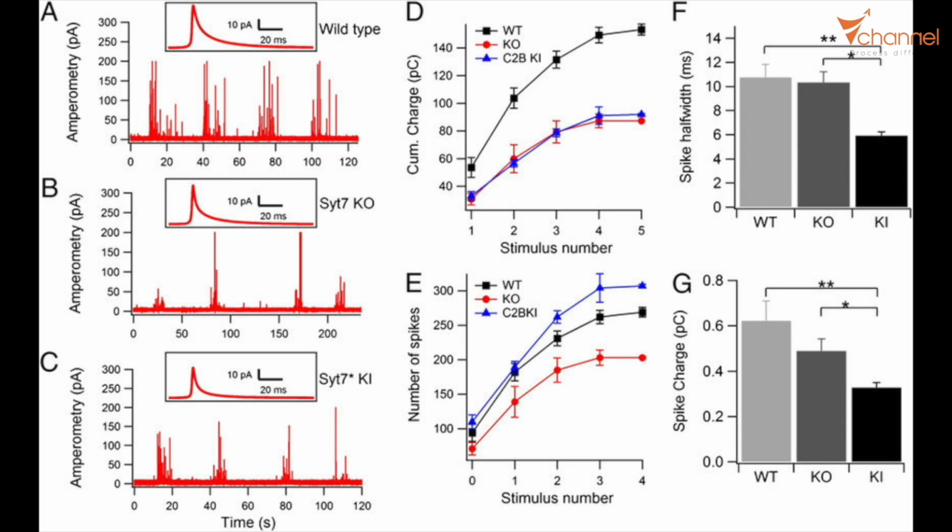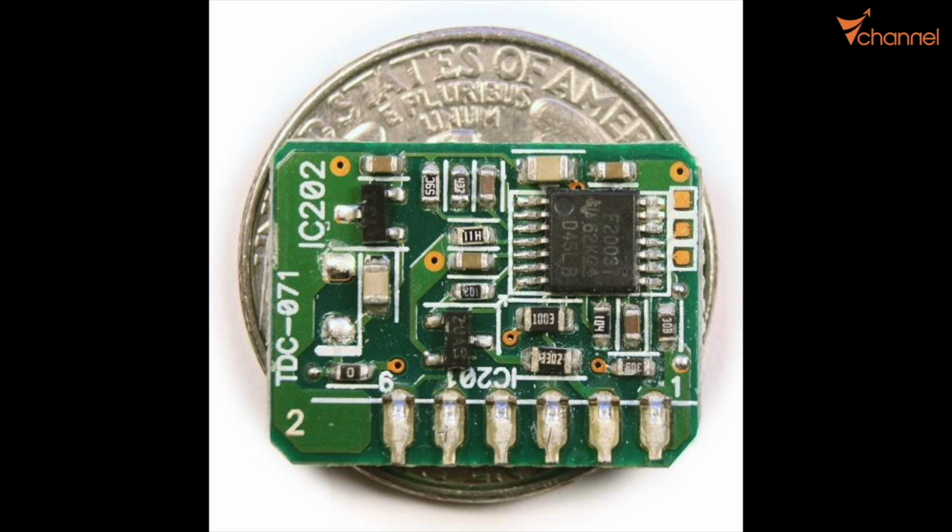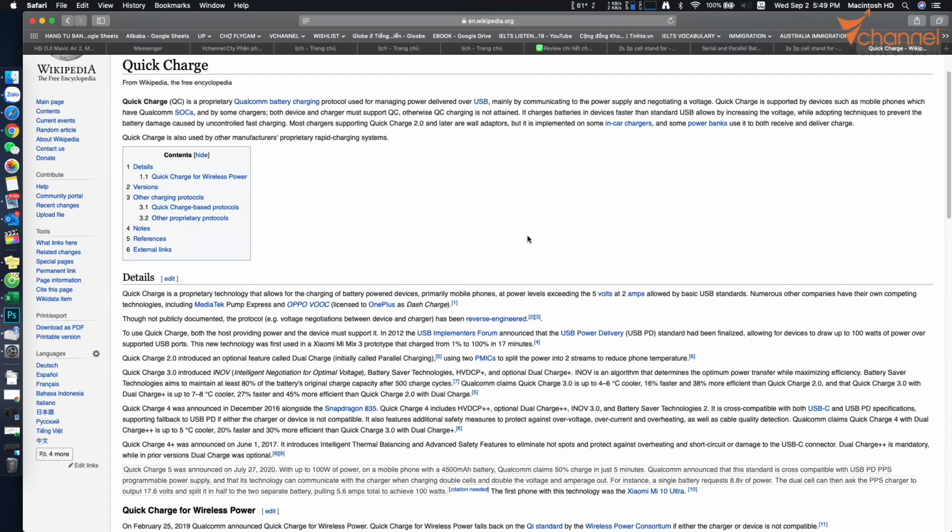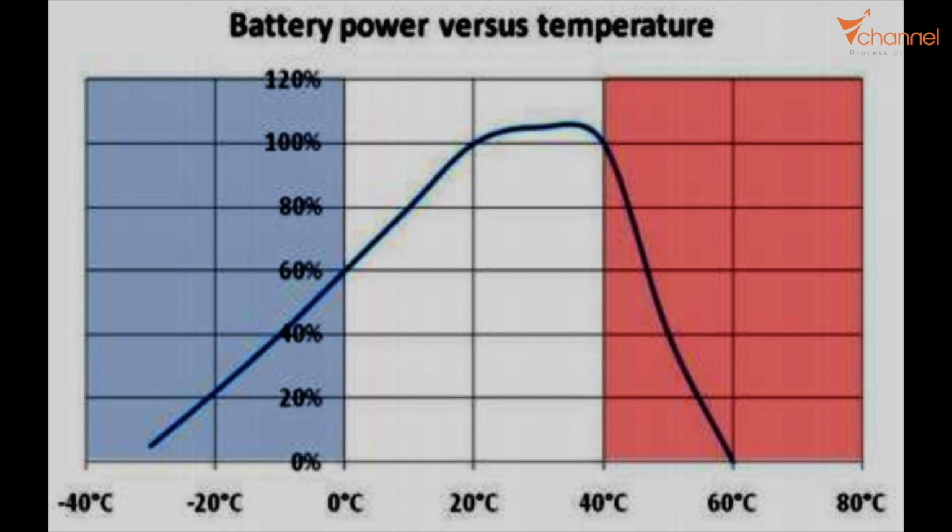It is designed so the electric charge current decreases when the temperature is high and increases when the temperature is low. That is an intelligent charger. An expensive charger has its own processor to control charge current. The quick charge technology at present uses that rule. It will adjust the electric charge current to be best for charge duration, endurance, and temperature.